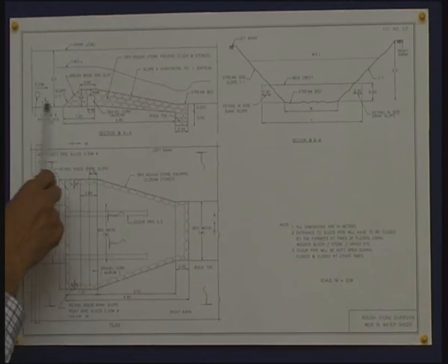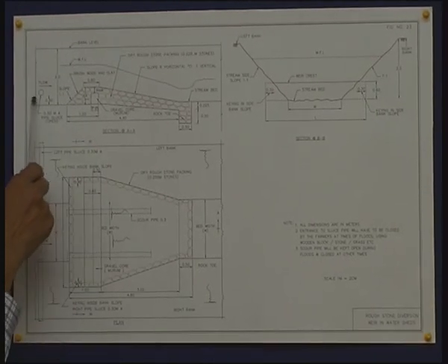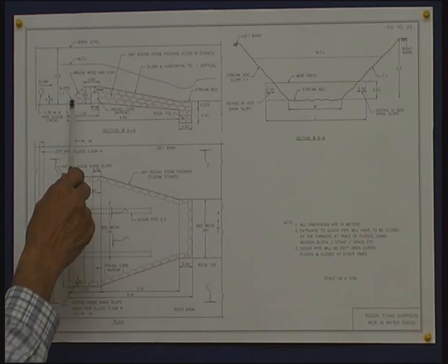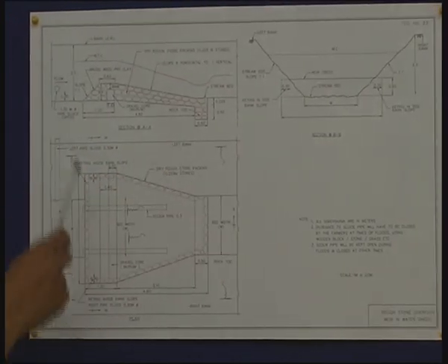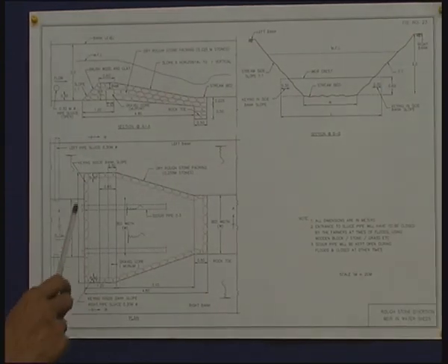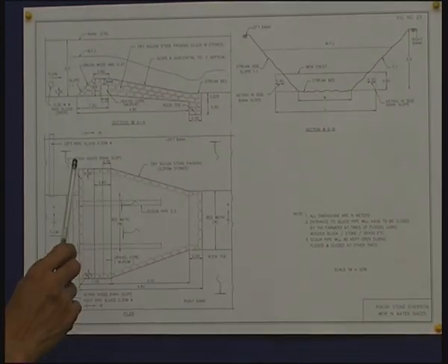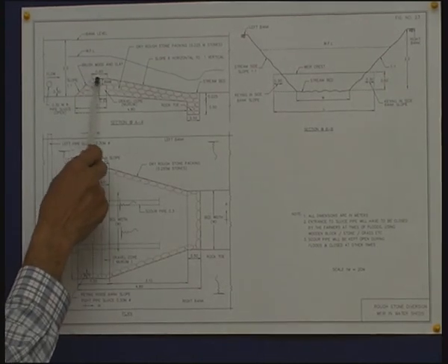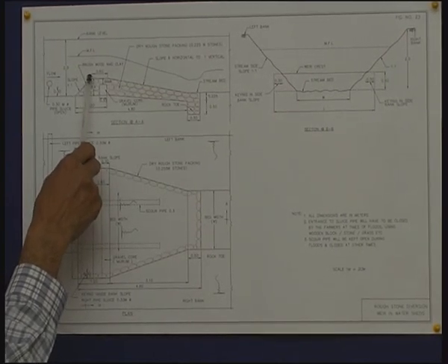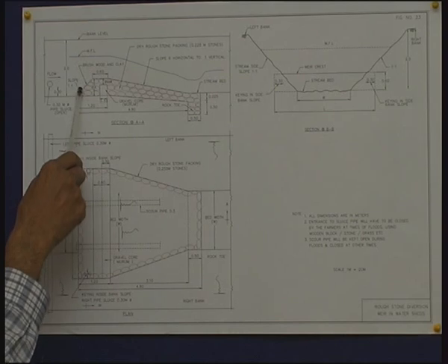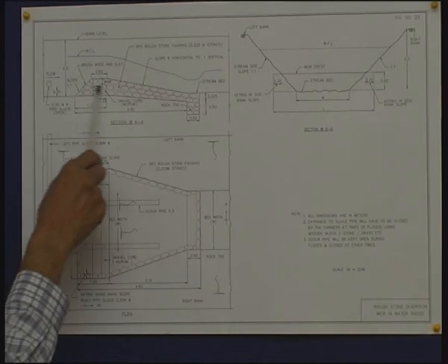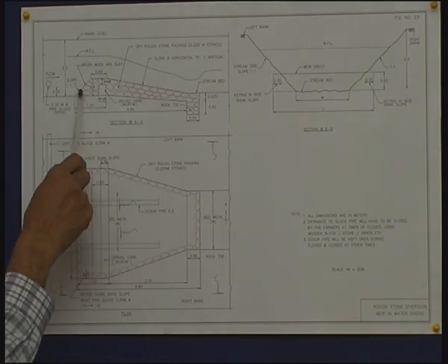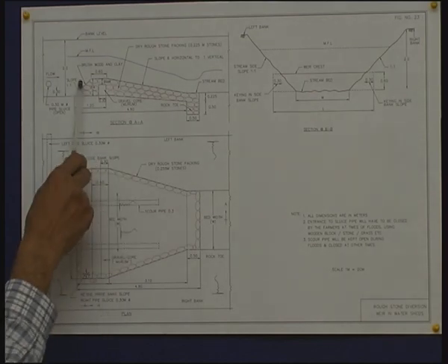So, therefore, the upstream portion of the structure will be free of silt when once we operate the scour vent, what we call it as scour pipe. And this scour pipe has got to be kept open throughout the flood period when the floods occur like this. And when the floods subside and the water level comes to the crest of the obstruction, then this scour pipe will have to be closed. The scour pipe otherwise will be taking away the base flows, will be taking away the spring flows. So, during the non-flood period, this scour pipe has got to be closed.